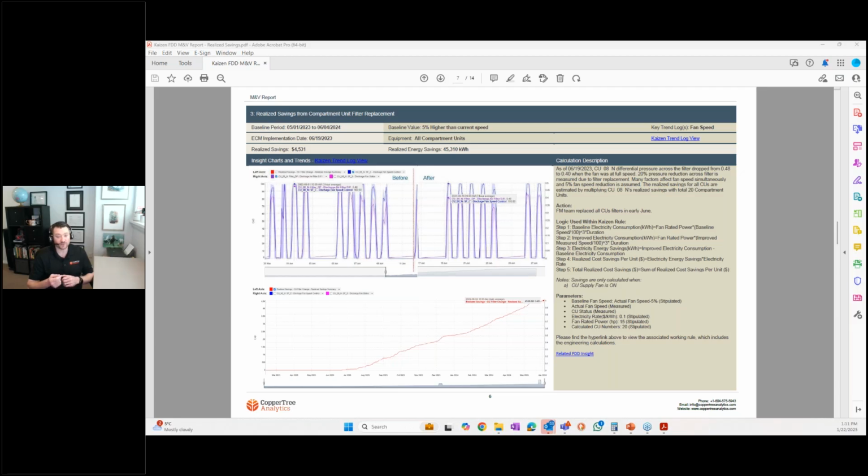As far as testing the sequences, we can generate conditions which would lead to that sequence being enacted, right? Theoretically, we could simulate demand, as I mentioned, simulate cooling demand. Maybe we lower the cooling effective set points really low, and we see what happens with regards to the sequences, both on the primary equipment and all the sequences along.